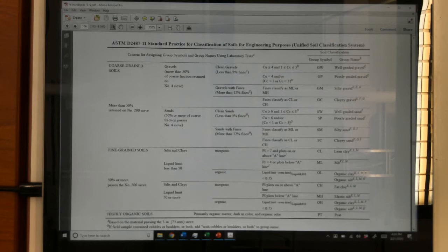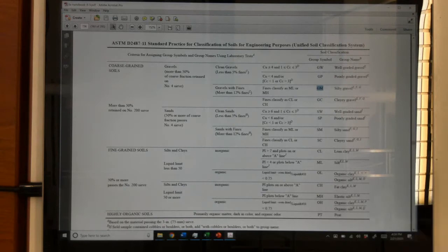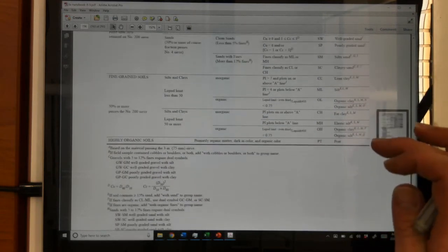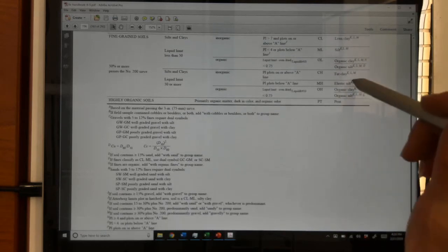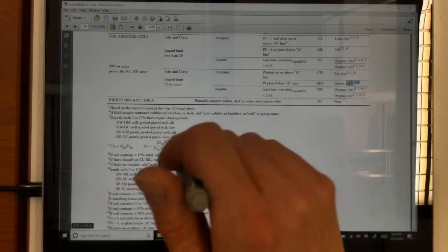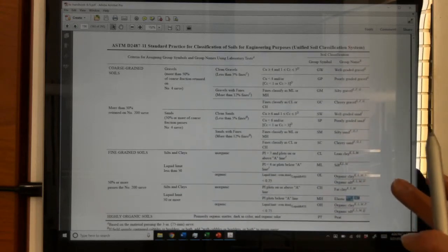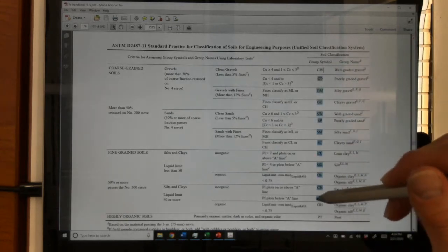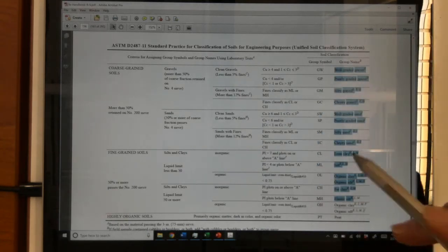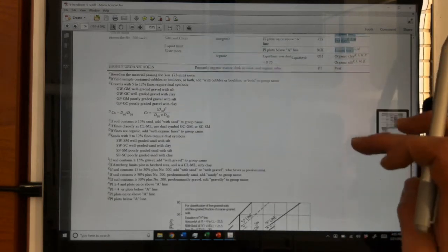This is the USCS table. And again, the questions here are going to be on classifying soils, but the ultimate thing that they want you to give is probably a group symbol. Here we do have some of the extra pieces where, just like in class, we said you have to pay attention to these superscripts and then go down to this part of the table to be able to really give the group name of a particular soil. So group symbol is sort of straightforward. Group name might have a little extra piece where you need to look down to these subscripts A through Q they have.